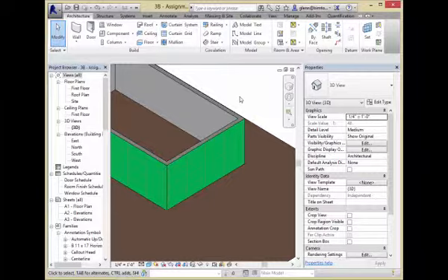If you were to export this file to something like an estimator, to get quantity takeoff and stuff, does he take into account those materials that you combine? Yes. You can have it actually report the quantities, so it'll know the amount of stud, the amount of sheathing, the amount of composite panel, whatever that is. And then in the estimating program, you'll go through and find in your cost catalog some material that you want to associate that with. It's actually very smart about tracking that, and it can make a really big difference between the inside and the outside surface.